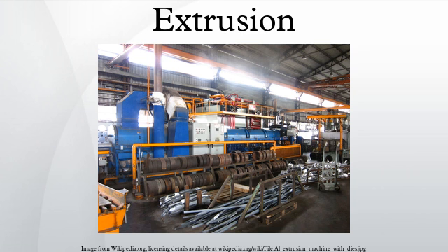Sharp corners should be avoided. For aluminium and magnesium the minimum radius should be 0.4 mm and for steel corners should be 0.75 mm and fillets should be 3 mm. The following table lists the minimum cross-section and thickness for various materials.